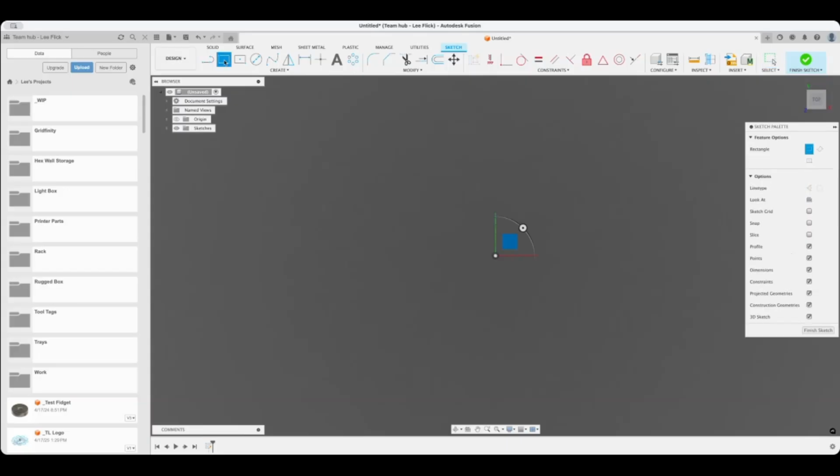So just for fun, let's grab the box here, the second one, the rectangle. If you see, the sketch palette over here should have lit up, and it should have shown your green and red on here, and then a rotate thing. If I put my mouse right on the center, it'll say place first corner. Now I don't have to put it there. I can put it anywhere on the screen, but click once, then move the mouse out, create a box, and click again. I have a box. Now, just for simplicity's sake, let's make it a cube. I just have a flat square box.